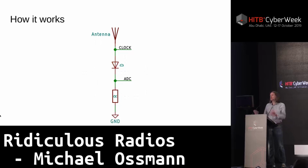And then the analog to digital converter measures the signal that's passed through the diode, through our mixer here. I call it a mixer because what it does is it combines the clock signal coming from the microcontroller with the signal from the antenna, and from those two different frequencies it produces additional frequencies. They're called mixing products, and one of those is the difference between those frequencies.